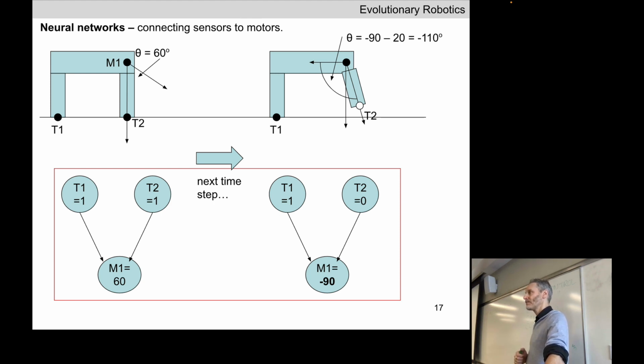Okay, so the physics engine is trying to apply a force to rotate these two pieces away from one another in a particular way, but based on other things that are going on in the physics engine, one or both of the parts, or in some cases neither of the parts, will actually move. In this cartoon example, this part has less mass. It has a little bit of friction with the ground, so it also takes a little bit for this thing to get going. We're simplifying a lot of things in this cartoon.